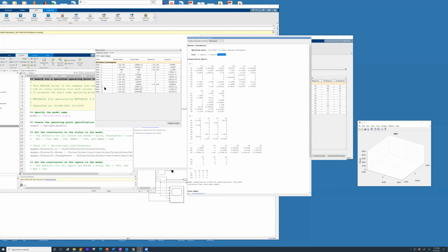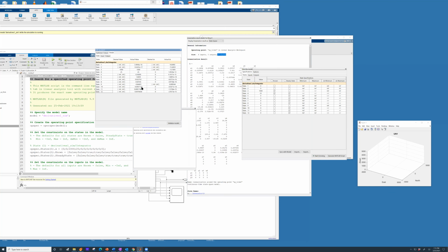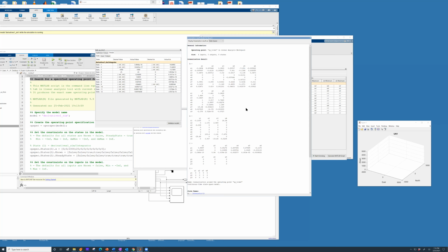So if you look at the PQR, the state is zero, derivative is zero. So that dynamics is not affecting the overall performance of the aircraft. So Matlab did the minimal realization, and now your reduced order model is 9 states.